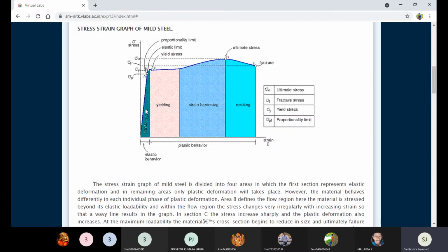We cannot expect the stiffness value of the engineering material after the plastic stage. Stiffness value is within the elastic limit, so this phenomenon is to resist the elastic deformation. If the material is allowed to deform elastically, it will definitely deform elastically until it reaches the elastic point. Above that we will reach the plastic point.